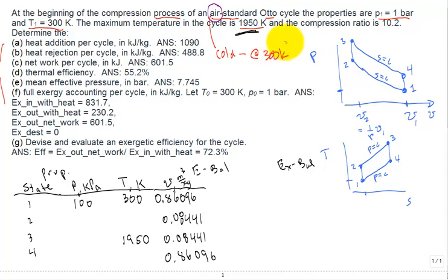But it didn't say cold air. All right, we look around in the problem statement. Did they say use C sub V equal to, or C sub P equal to, or k equal to? Nope, they didn't give us any particular values of C sub P, C sub V, or even k. Even if they just gave us k by itself, we could get C sub P and C sub V.